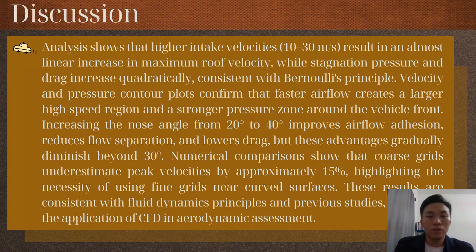Numerical comparison shows that a coarse grid underestimates peak velocity by approximately 50%, highlighting the necessity of using fine grids near curved surfaces. These results are consistent with fluid dynamics principles and previous studies, validating the application of CFD in aerodynamics assessment.